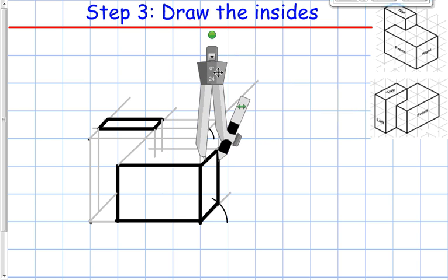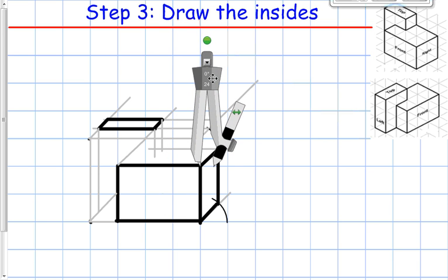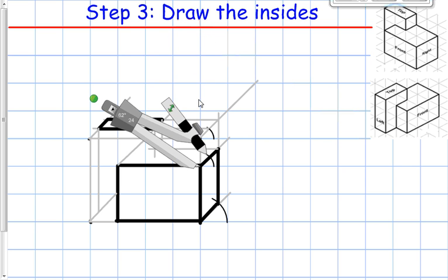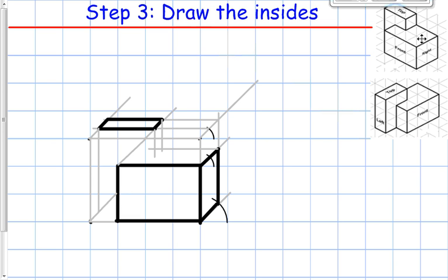We're going to start right here because I want this line to show me along here basically where this top ledge will start. So I'm going to take a construction line, go right to where this meets right here, so it should be about halfway back, and I'm going to stretch this all the way across, because I'm going to start to fill in object lines to show why we're doing this. It's going to give me a few different lines.